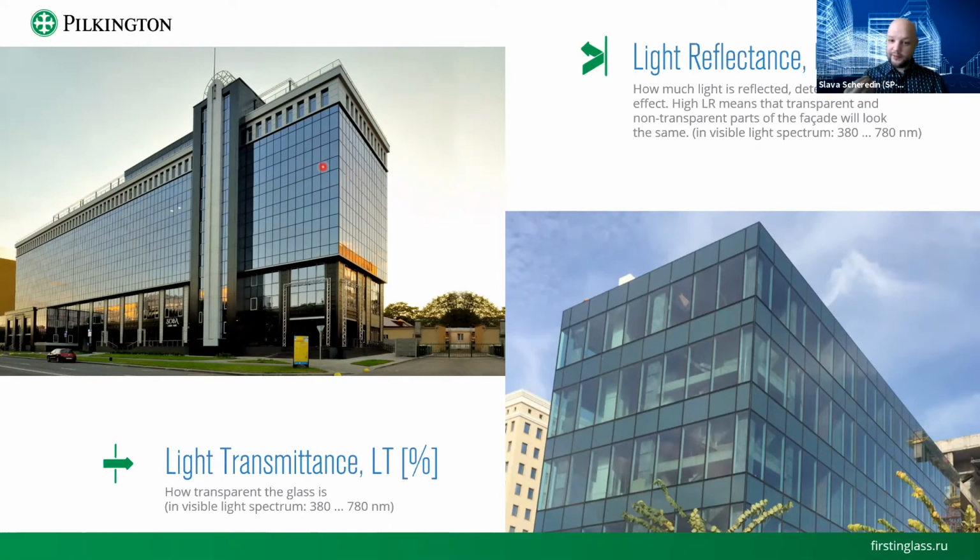Transparent non-reflective glass helps you to create very transparent facades, but they will not be uniform whatever you do. So depending on the architect's choice, or whoever is the decision maker, you need to consider different options for glazing. With this, you may think, okay, then reflective glass is good because a uniform facade is great.